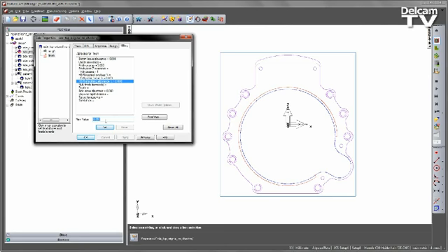In this case, I'm going to change my smoothing allowance. I'm going to add a smoothing allowance of 30%. This will allow my stepover to vary by up to 30%. In this case, I'm hoping to see some more direct or straight line moves as we get to the extremities of the toolpath.